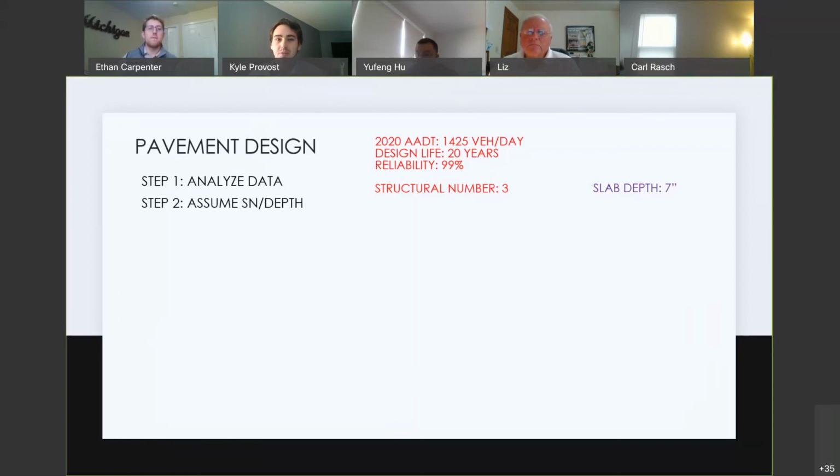This is the point where we analyze our pavement alternatives. We selected 5 different criteria and weighed them to what MDOT would hold most important. With cost and life at the highest priority and aesthetics at the lowest priority, we continued with a flexible HMA pavement design throughout the rest of the project.